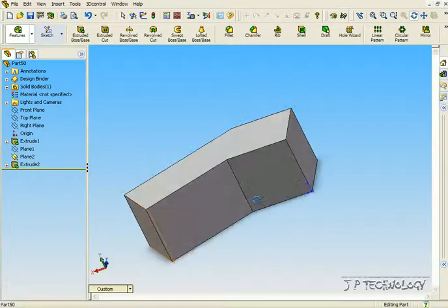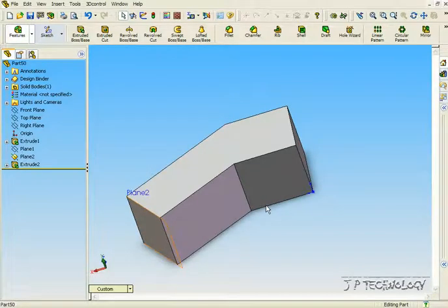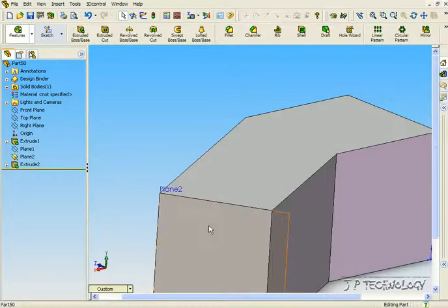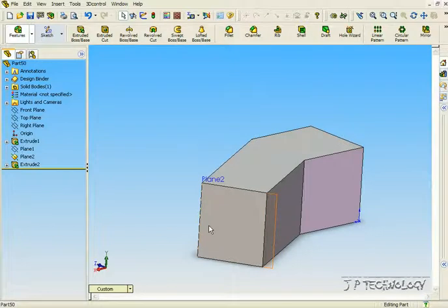So you can use this when you're in a sketch such as this, if you're in a part and there are different planes that you're working off of, you're able to extract and pull from other parts and planes. So using convert entities, it's just like you're at a view, and then you can pull all those lines onto your view, and then you can play with it. And all those lines that come onto your view are directly perpendicular to what you're seeing. You're pulling straight out. So like I showed how the 50 mils turned into the 43.3, that's how much of the line you're actually seeing at that plane and at that view and that orientation.